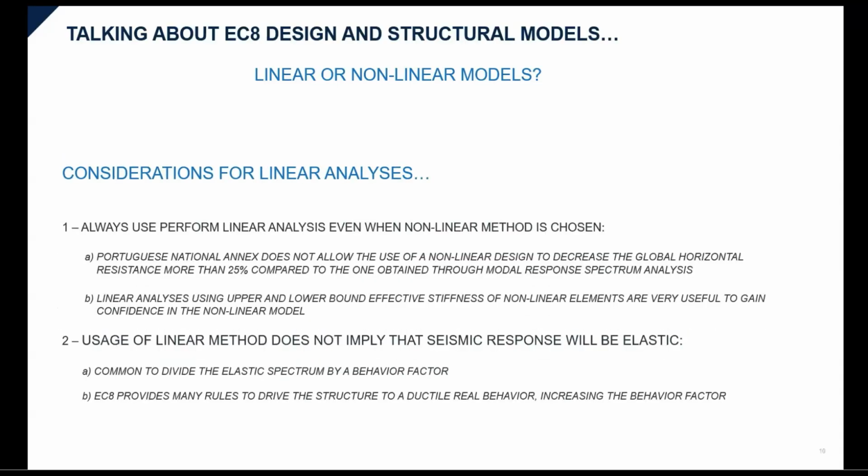Some simple considerations for linear analysis. Even if we need to perform nonlinear calculations, we should always use a linear analysis. In some cases, there are even restrictions on what possibilities we have for using nonlinear analyses to guide the total behavior or resistance of the structure according to the results we obtain from the response spectrum analysis. As mentioned earlier, linear analyses can be very important for defining an upper and lower bound of stiffness and results so that we can have some level of confidence in our nonlinear model.